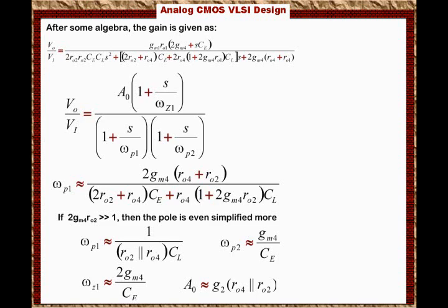So the amplifiers usually do not amplify high frequency signals, and usually the gain dies at high frequencies. So part of the challenge or the trade-off also is how could we increase the bandwidth of the amplifiers, right? So you have to go back and minimize the capacitances and the resistances, and by minimizing the resistances you end up with lower gain, so the gain and the bandwidth is a trade-off.